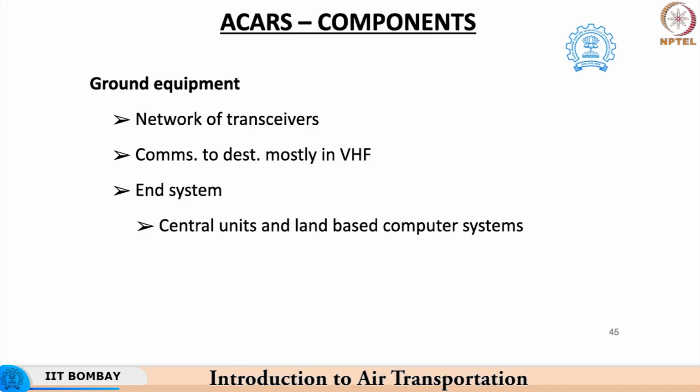The end system related to this ACARS is called the central unit, the land based computer system, which basically decodes the underlying messages, and based on this overall decision, instructions are provided to the ground controller, and subsequently transmitted back to the aircraft.